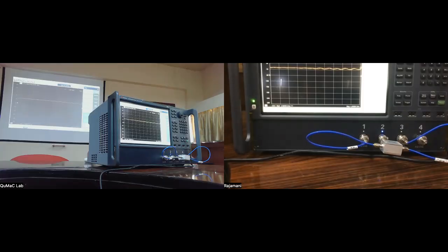The thing which typically happens at high frequencies is that your resistor will no longer remain a pure resistor. It will have some impedance. It will have some capacitance to it, some inductance to it. So it will now develop other kinds of frequency responses, which basically cannot be explained by a simple resistor model. That's what happens when you go to high frequencies.